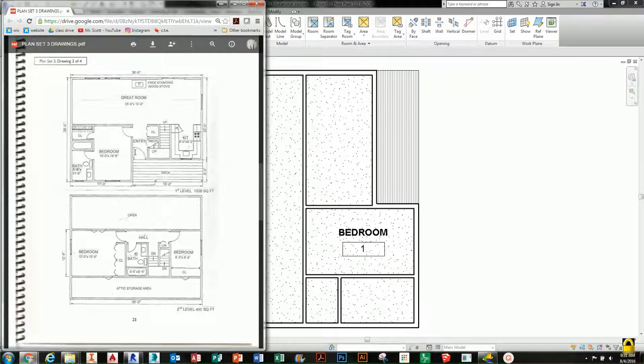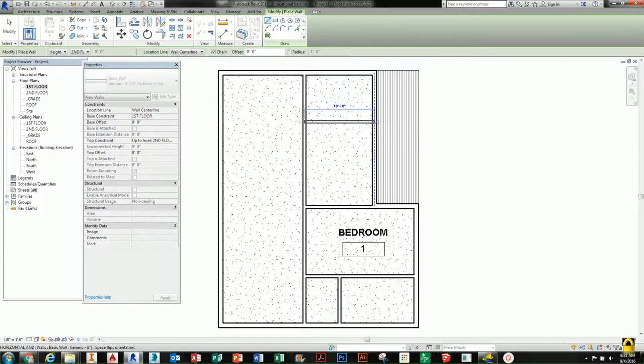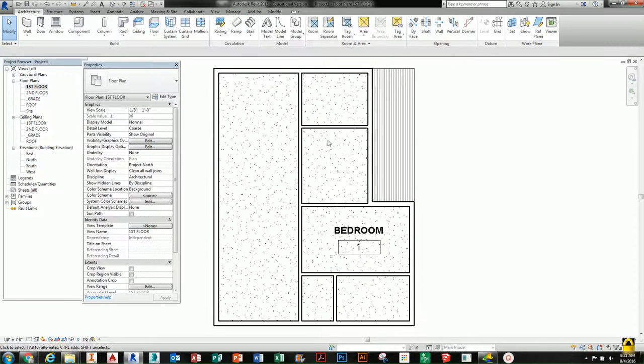We have an entryway, so we're going to go 4.5 or 5 feet here. Then we have 2 sets of stairs. That's another 6 or 7. But let's start from the other way. Let's do the kitchen. It's 8 by 9. So I guarantee this right here is going to be our 8-foot mark. So we're going to make a wall. Click on this wall, make it 8 feet. And now we've got our kitchen, and we've got some area for our stairs.